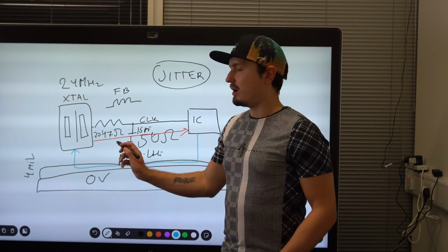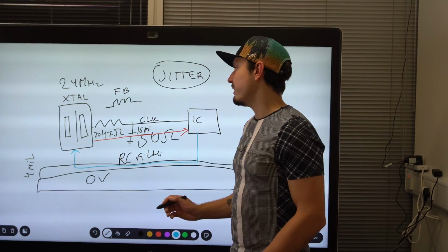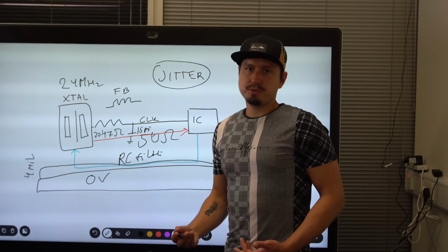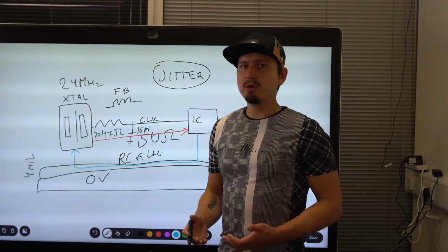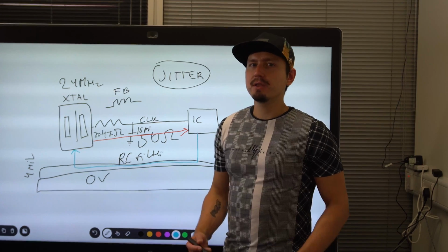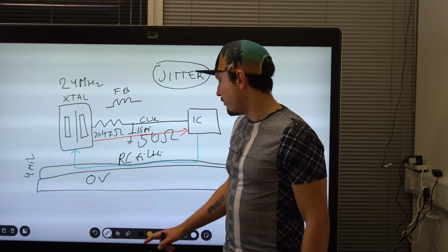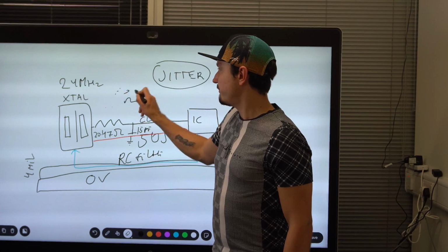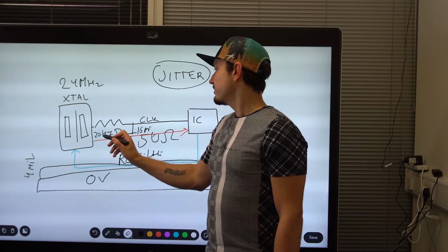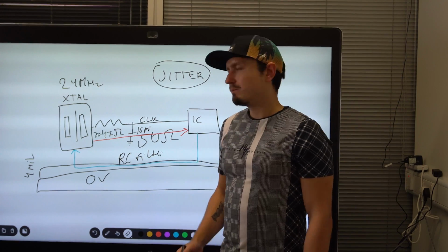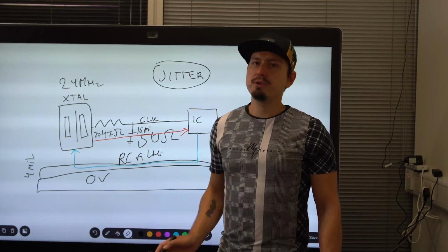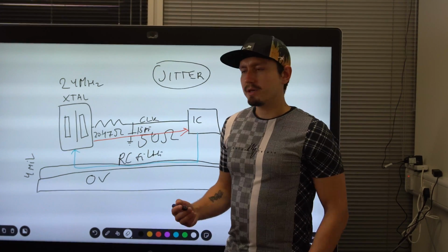What is the shortest path and the lowest impedance path, and how can I minimize it as a designer, so that I know exactly where all my currents are flowing on a printed circuit board? This is really what we're aiming for, and not adding ferrite beads or gigantic resistors into the path of the signal, because even though that gives us the result we want, it is not the way to do it, if you know what I mean.